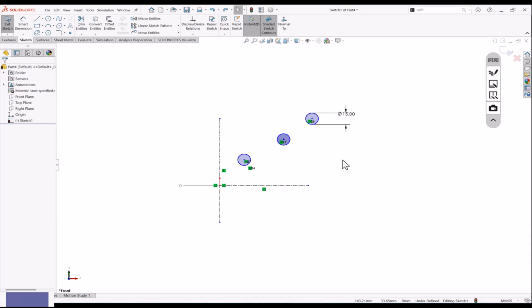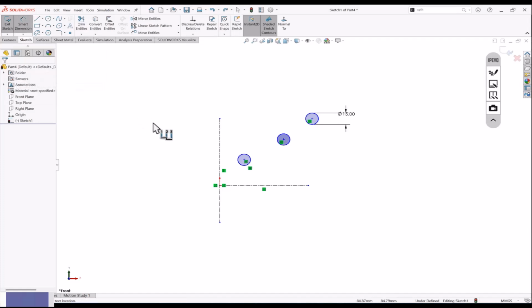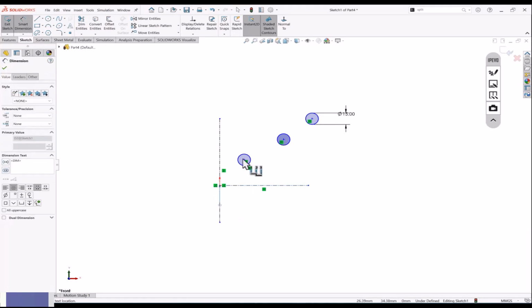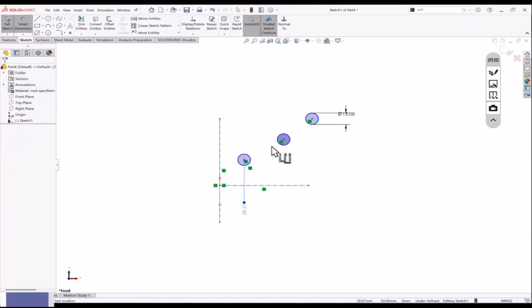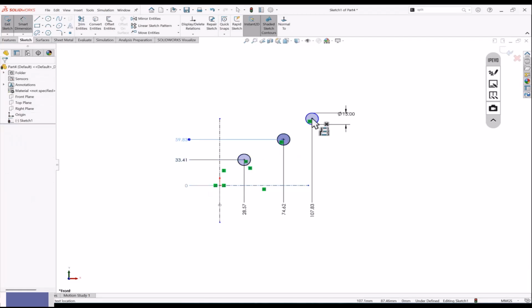You can do the same thing with horizontal and vertical. Same as what we have learned here now. You take this horizontal and just add one 0 for the horizontal side and just do the dimension for that. Then again, you want to show the vertical side. You go for vertical, make this 0, and click and add all sides to be 0 or dimension for that, the coordinate for that. So we are finding the coordinate location for each point. Both ways you can use, with ordinate or with horizontal and vertical separately.